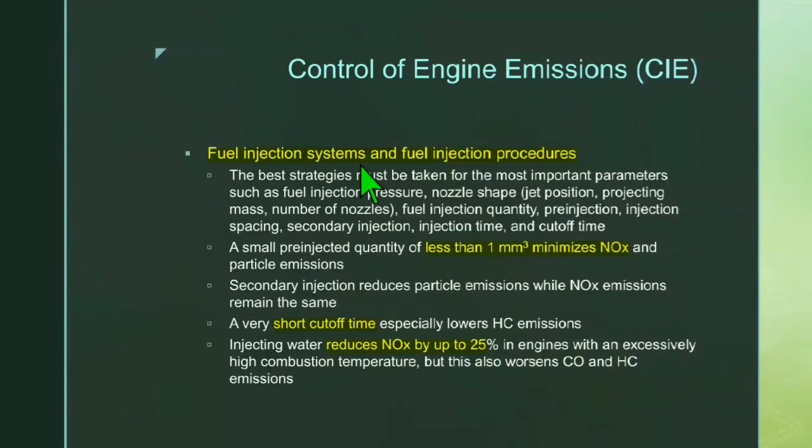Fuel injection systems and fuel injection procedures. The best strategies must be taken for the most important parameters such as fuel injection pressure, nozzle shape like jet position, projecting mass, number of nozzles, fuel injection quantity, pre-injection, injection spacing, secondary injection, injection time and cutoff time.